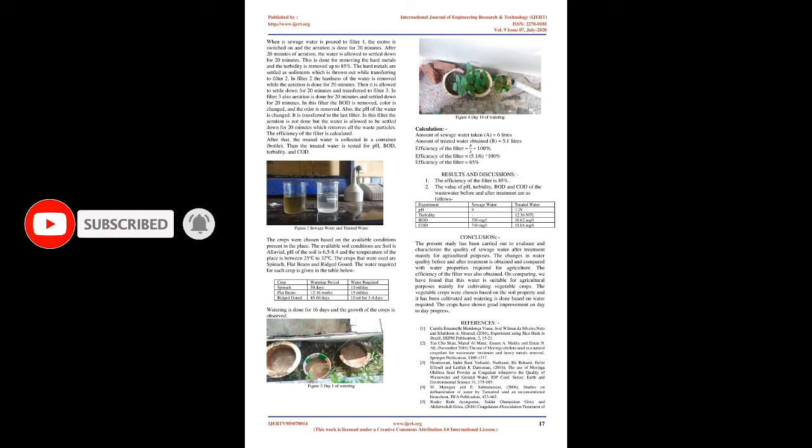Methodology. The tamarind seed powder in filter 1 is prepared using the following method. Step 1. Tamarind seed is soaked in water for about 3 hours. Step 2. The soaked tamarind seed is left to dry under the sun for about a day. Step 3. Finally, the tamarind seed is finely ground, and it is allowed to dry at room temperature for about an hour. The drumstick seed powder in filter 2 is prepared by this method.